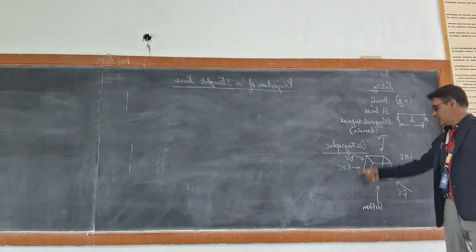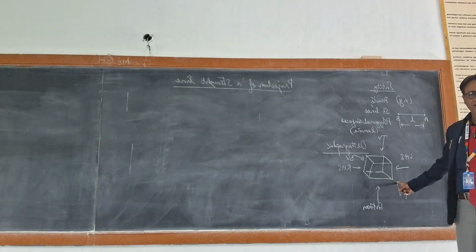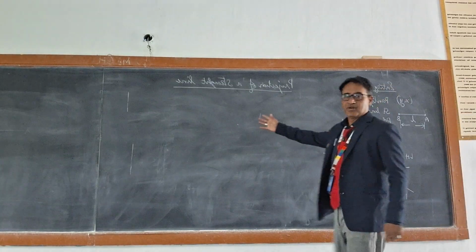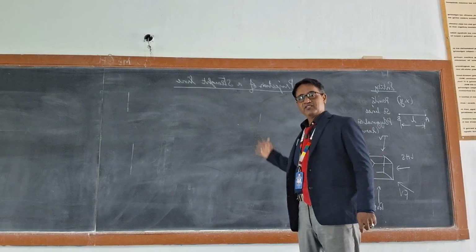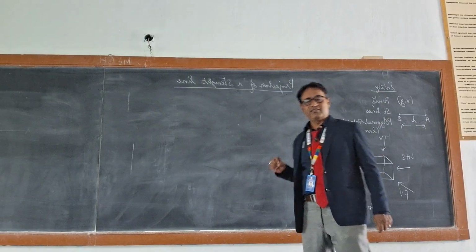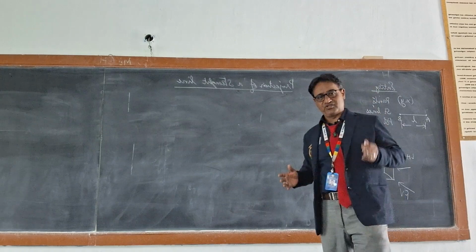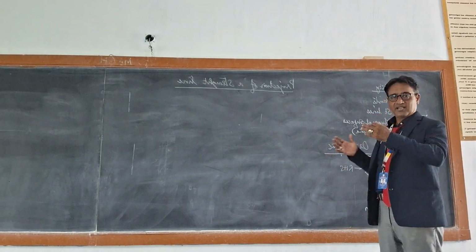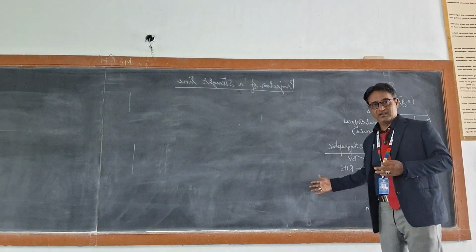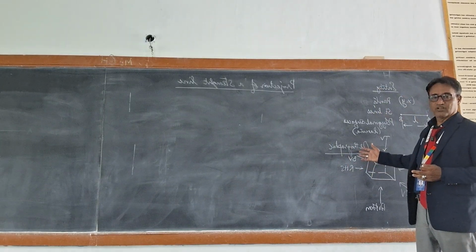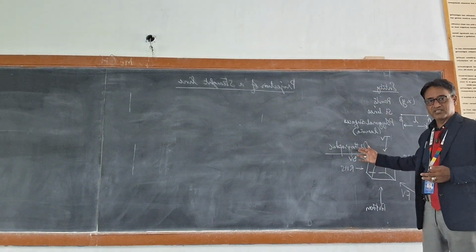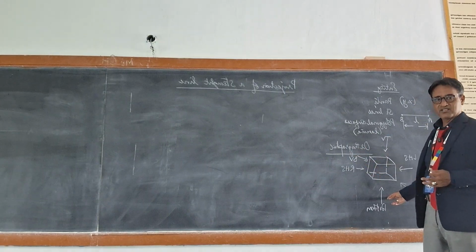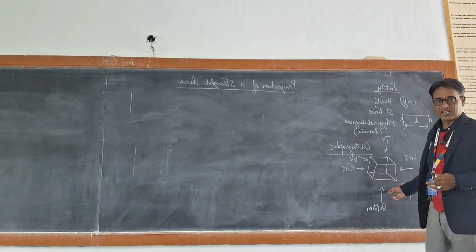So if you want to understand the definition of this object, which is a 3-dimensional object, but my limitation is I have a 2-dimensional plane, then I have to define this object onto this 2-dimensional plane, which we normally call a transformation. And if I am doing that from the right angle perspective to the projection plane, then you call that projection an orthographic projection. So orthographic projection is nothing but defining the object with respect to different viewing directions. The maximum possible is 6 viewing directions.